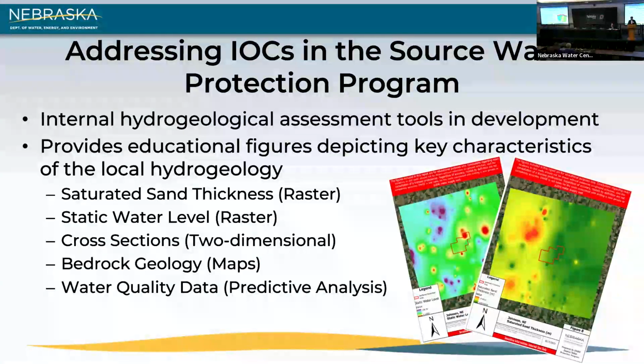We are basing these toolboxes off of our existing databases, such as the Registered Wells database, formerly in the Department of Natural Resources, now under DWE, and the Groundwater Quality Clearinghouse. Up on the slide here, we can see images that were calculated from one of the trial runs of the toolbox that calculated the static water level as well as saturated sand thickness. We can see in the top figure that's up on that slide with the red and yellow, the areas that are in red are areas where there's increased saturated sand.